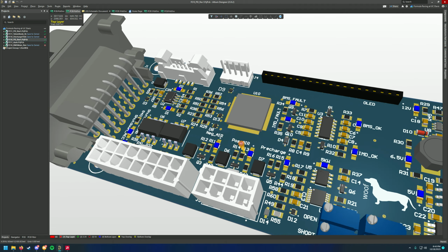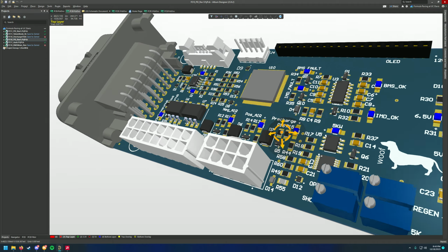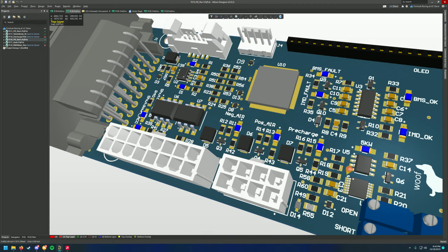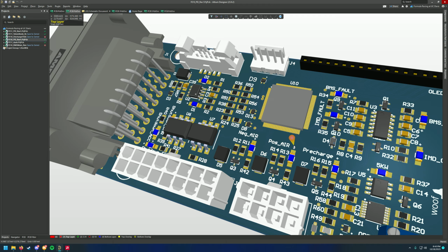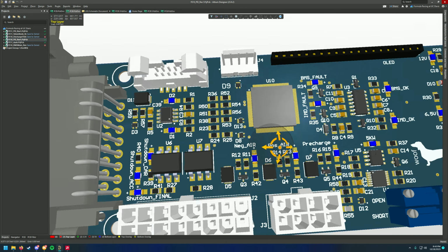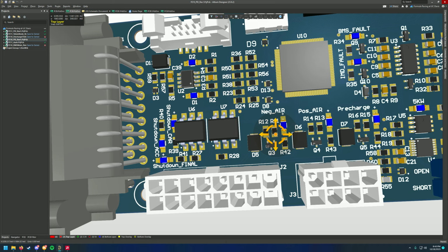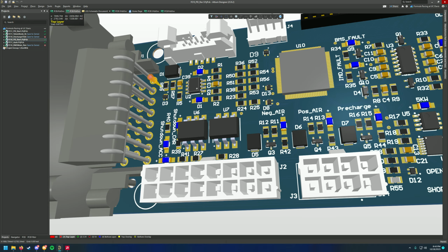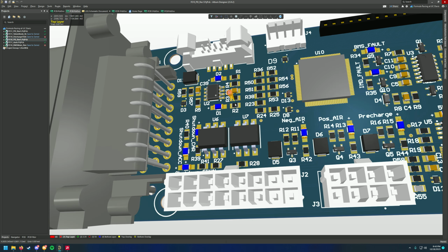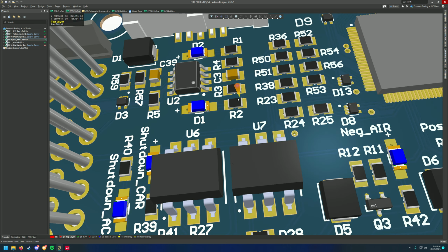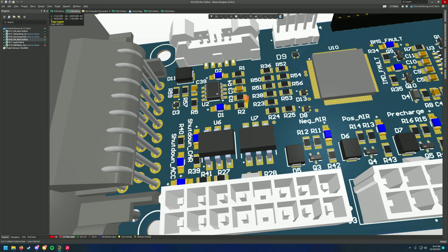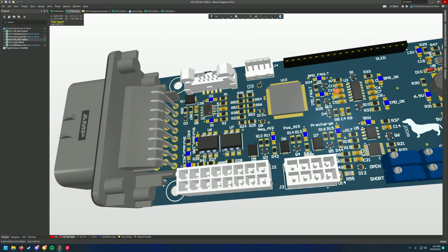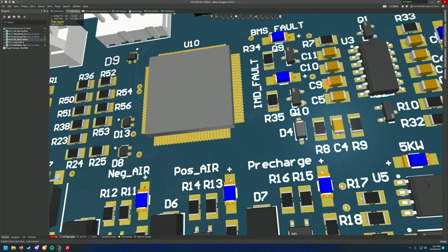The other advantage is it's just a smaller package, typically, so you can fit a lot more components in a smaller space. It's also easier for a machine to assemble these parts. How you do it in production, or at least for our small scale of production, is instead of individually soldering all these components, you make a stencil which has holes for every component you want to solder, and then you put solder paste over the stencil so that you leave a little bit of solder paste.